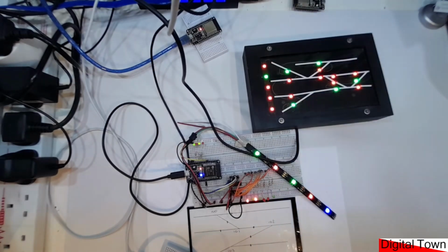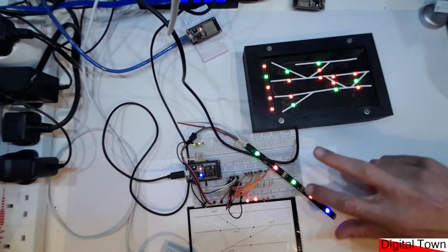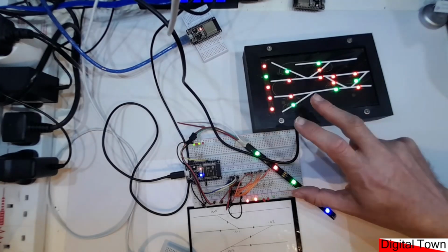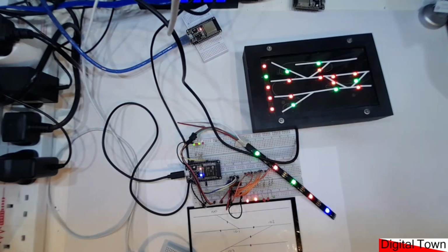This is because in this particular situation both are on the same layout address, and these could be two control panels at opposite ends of a layout that are both sending commands to exactly the same accessory decoder and are both receiving panel updates to say that something happened. So that is why the panel update is separate from what I would call a standard accessory decoder system.